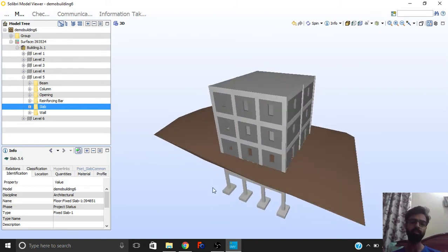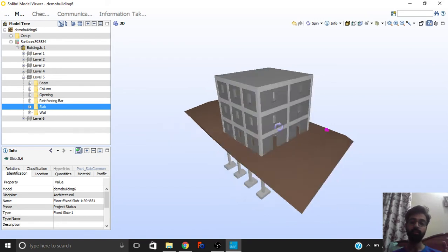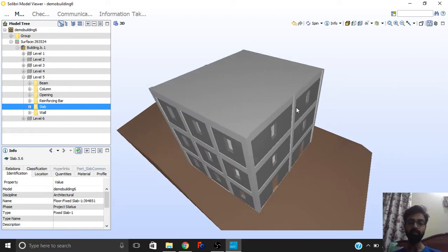Based on that geometrical information, we made patches. We made the IFC file, then the IFC file was opened in FreeCAD, the open source BIM software, where we have a function inside. Through that we made the grouping of rebars and saved that file in FreeCAD. So our rule engine opens this IFC file along with the FreeCAD file, where we can do the backend operations and then apply our checks, all the digital formulas.